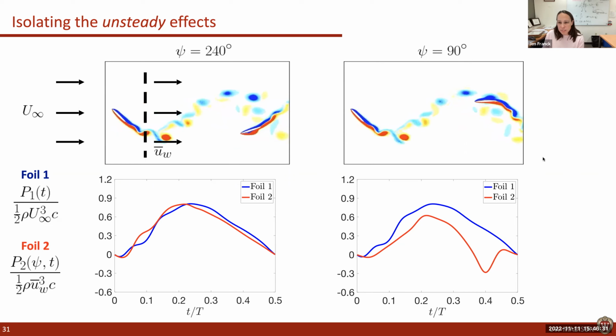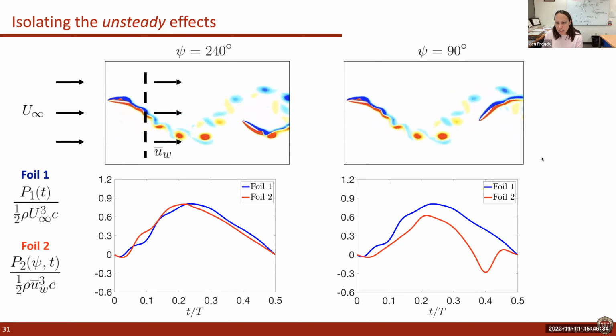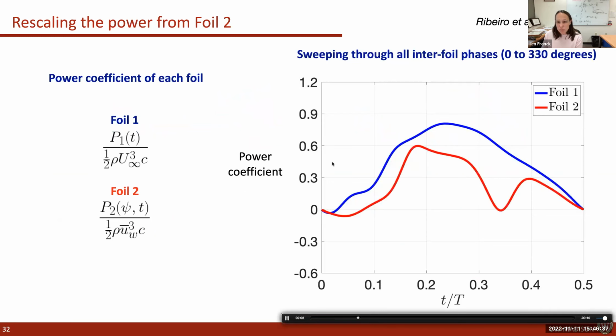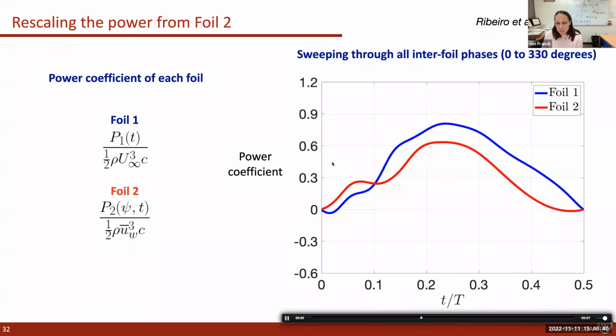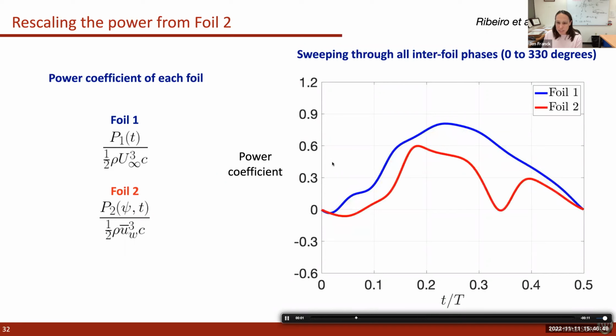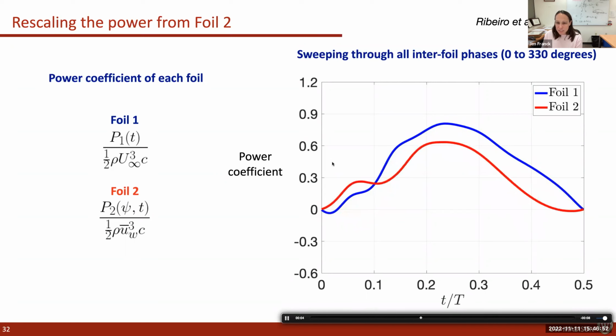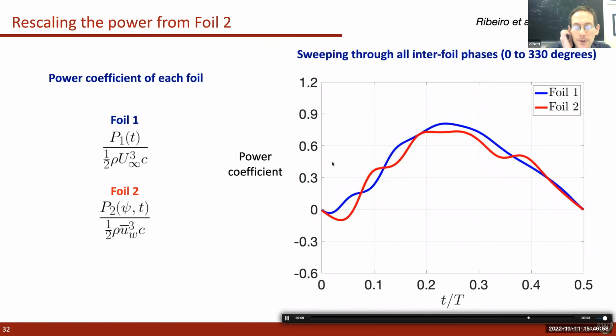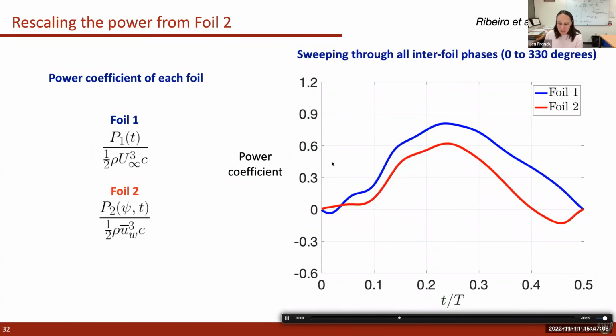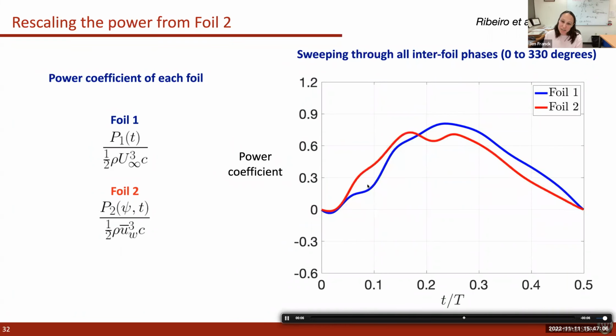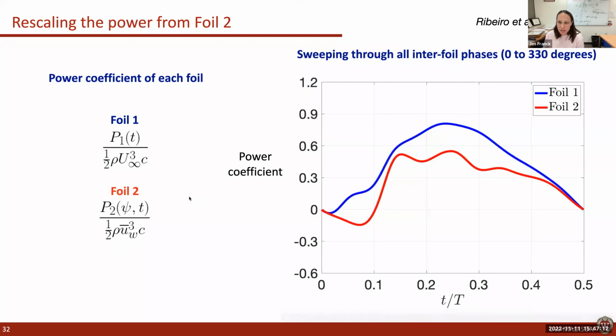So this is an example of these discrete vortex foil interactions. If you think about sweeping through all of these phase angles, you can watch this evolution. And sometimes the red line goes slightly above the blue line, but for the most part, it will stay equal or less than the blue line. So you are seeing these destructive interactions. So colliding with those vortices from the upstream foil is generally not a good thing. Yes, correct. In this configuration, although sometimes you see slight benefits, in this tandem configuration we're seeing mostly destructive interactions.